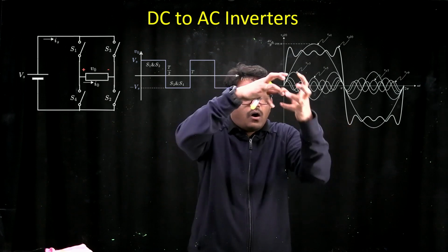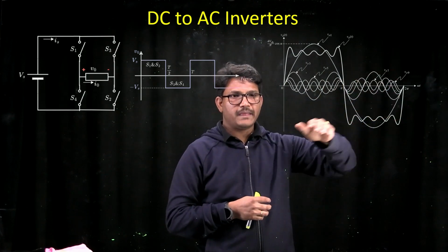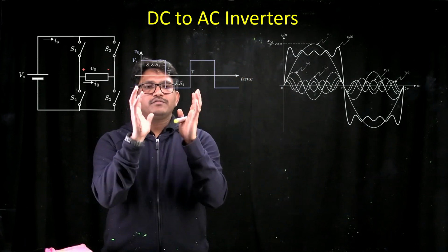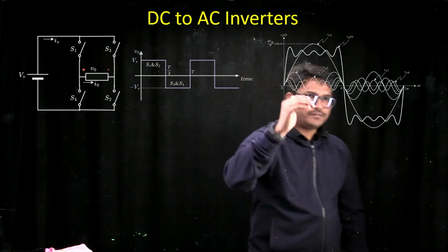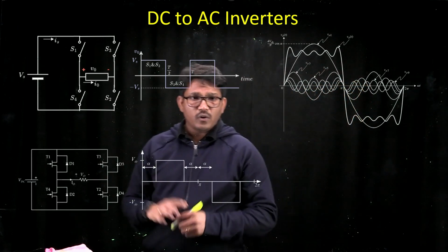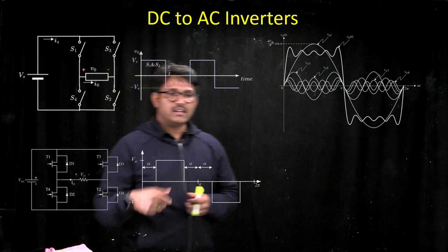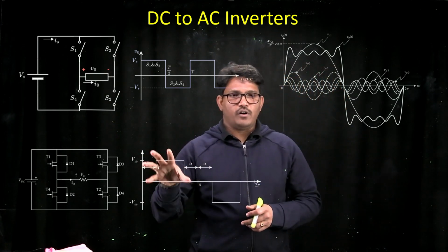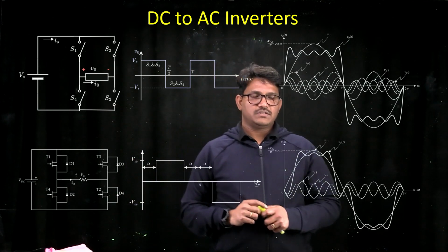So when you combine all that, the fundamental, third order, fifth order, seventh order, ninth order frequencies, then the output voltage you get will be close to your square wave. Means the square wave that we have here is the combination of the fundamental, third order, fifth order, seventh order, ninth order, and so on frequencies. But when you follow a different switching sequence, where you have 4 different switching conditions, and you could get positive, negative, and 0 voltages at your output, then when you select your alpha equal to 30 degrees, this is what your output voltage is.